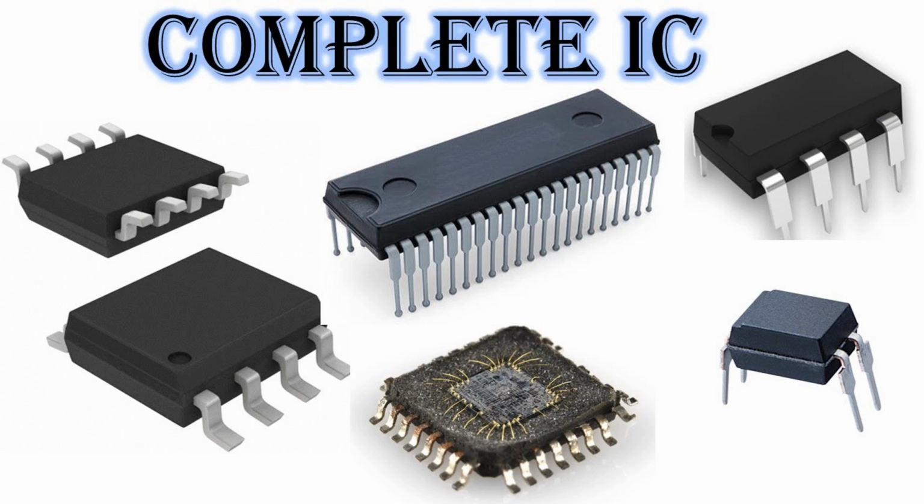Types of counters. There are different types of counter ICs, including up counters. These increment the count for each input pulse. Down counters. These decrement the count for each input pulse. Bidirectional counters. These can count both up and down based on control signals. Decade counters. These are designed to count in decimal, 0 to 9, and reset to 0 after reaching 9. Binary counters. These count in binary and can have various modulus values.